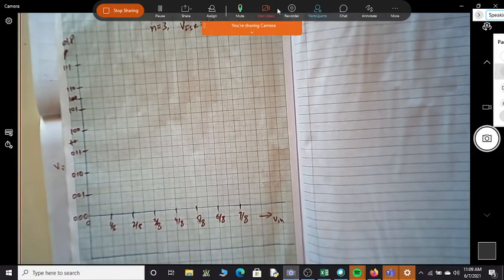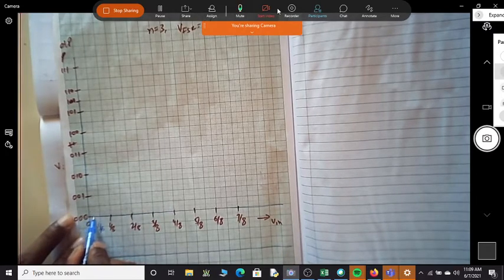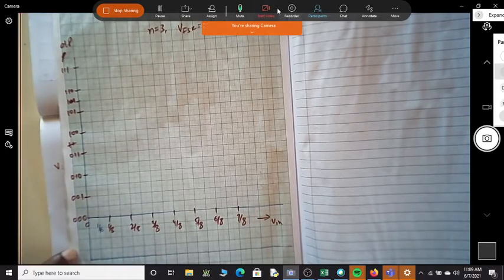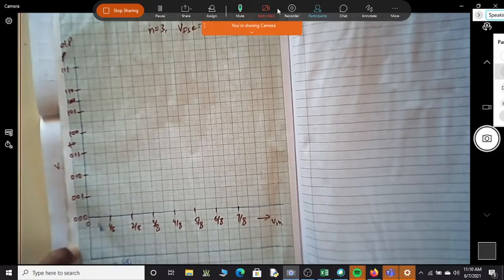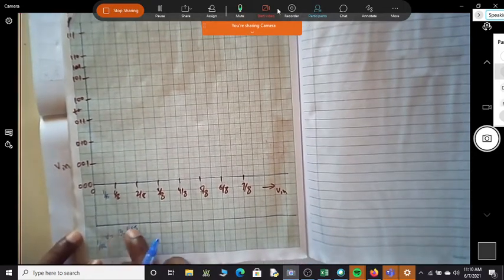Ideally speaking, under ideal conditions, what will happen is that we are supposed to have, till 1/16th of a volt. What is this 1/16th? Actually, 1/16th volt is nothing but half LSB. This is half LSB, 125 by 2 millivolt. So this is half LSB.